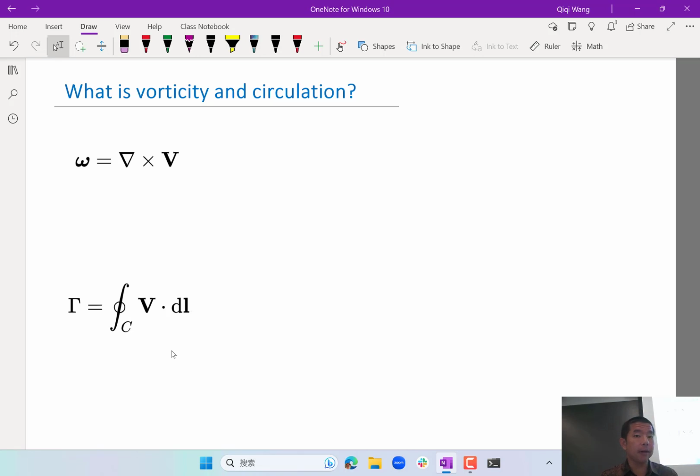And the physical significance of vorticity is the following. If we are able to put markers in the flow field, let's just use a bunch of markers that forms a cross. Just imagine putting a little bit of dye in the flow field that forms a cross, and we let the dyed flow evolve with the movement of the flow field. Vorticity essentially tells us how this cross is going to rotate.